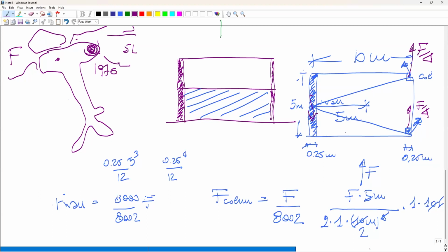It's also a matter of deformation capacity, inelastic deformation, because you want that big amount of energy, which is the earthquake, to pass through the structure and deform it, so that at least the column remains a little bit like this, but does not fall down. And we will see tomorrow how we can deal with this, because this can bring second order effects. That column was not designed at all for that demand.